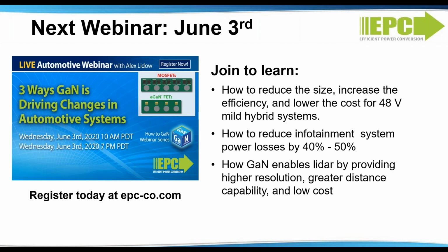You've showed a 3-level converter and then the dual phase buck converter. Which of those would perform better in terms of EMI? I think the EMI would be the same. EMI is generated from a few different things, and there's a lot of misconception about it. eGaN devices from EPC have no package.